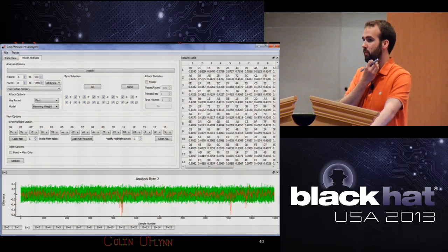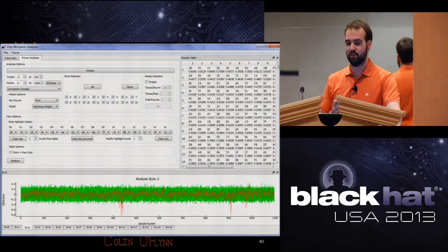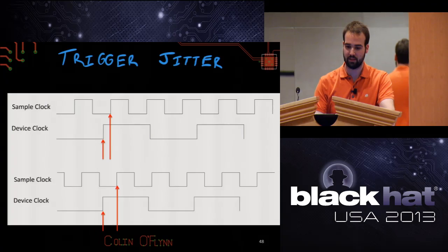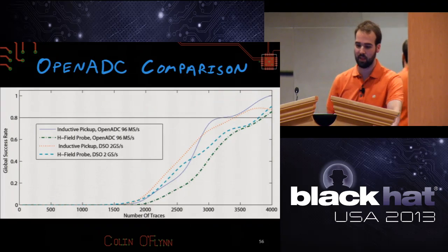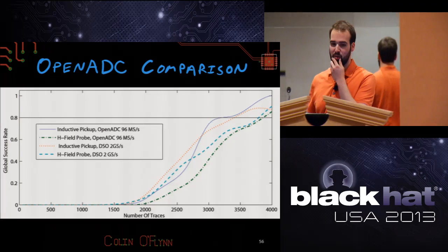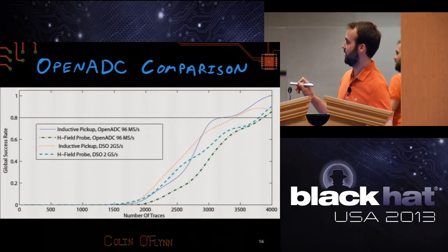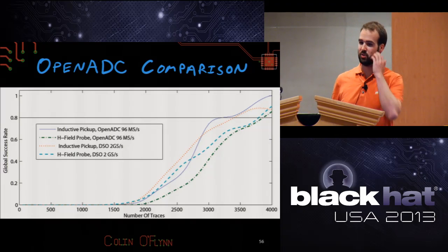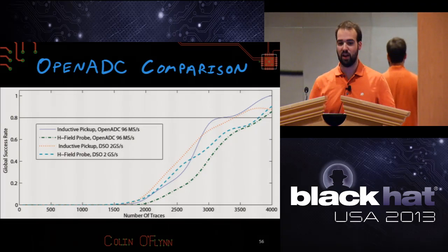Even if it's processing multiple bytes simultaneously? Yeah, so even if you do hardware AES and you do 128 bits at once, this works fine. In particular, this slide here, I didn't actually talk about. This is talking about a hardware AES implementation. The hardware AES is running at 24 megahertz, and it takes 10 clock cycles to do a full AES, which means it's doing all 128 bits at once on every clock cycle.